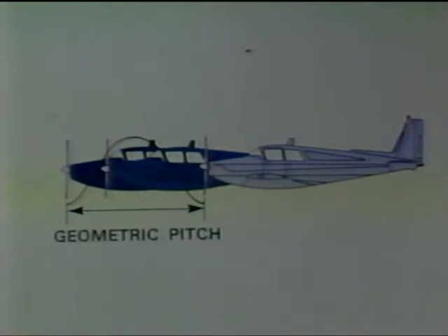Propeller pitch is the distance that a propeller will move forward in one revolution. This is more properly called geometric pitch and is theoretical in that it does not take into account any losses due to inefficiency.